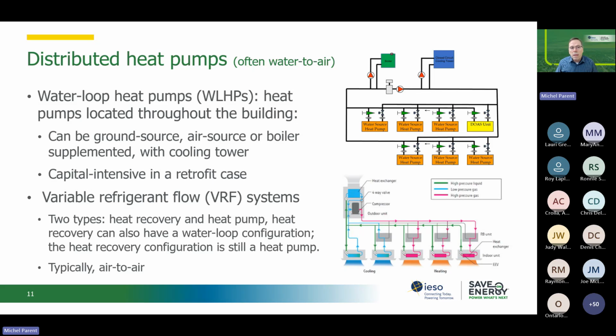When you have a VRF that's a heat pump only system, all your interior units are either in heating or cooling. A few years ago, those systems could not be integrated into a BAS, which was kind of a pain, because you ended up with two different control systems. Now, VRF systems typically have BACnet compliant controllers. So you want to make sure that if you get a VRF system, it is BACnet compliant if you have a BACnet BAS, so that you can actually integrate that properly into your system.